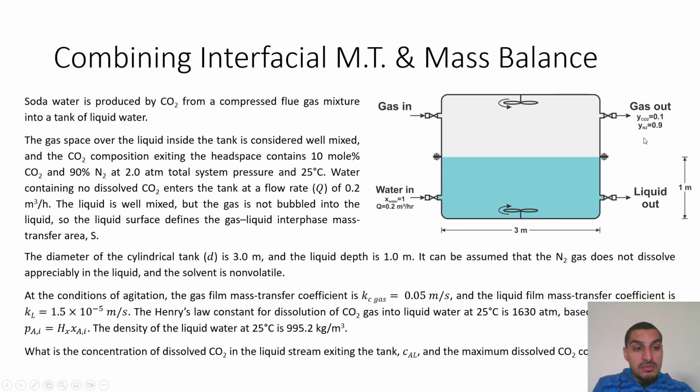So by knowing that this is perfectly mixed, and by knowing that this is the outlet concentration, we can tell that the concentration inside the tank in the gas phase is what we have here. And this is a very important part of the solution as well, that the concentration coming out of the tank is the same as the concentration inside the tank. So this is very important to keep in mind.